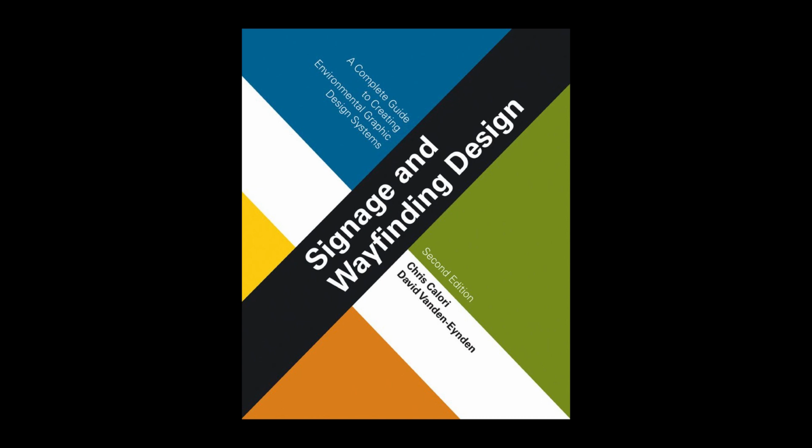A checklist guide for the drawings package content includes listing of the graphics vocabulary, including the full fonts of all typefaces, along with all symbols and arrows used, summary of all colors, materials, and finishes used in the program, front, side, and top views of each sign type with callouts, representations of the different graphic layouts for each sign type with callouts, mounting elevations, fixing signs in relation to architectural or site features, sign location plans typically bound in with the design drawings package.